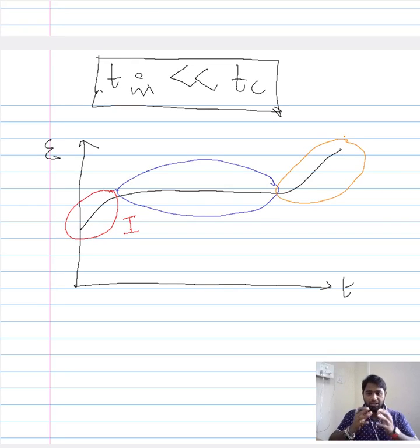Here, when the time taken for the instantaneous creep is relatable to that of the overall time, then stage 1 would include both instantaneous creep and transient creep. But if the time taken is insignificant when you compare it to the overall time period, then your stage 1 will exclusively comprise of the transient creep. This is something you need to understand, and depending on the creep plot that is before you, you need to appropriately define stage 1 of it.